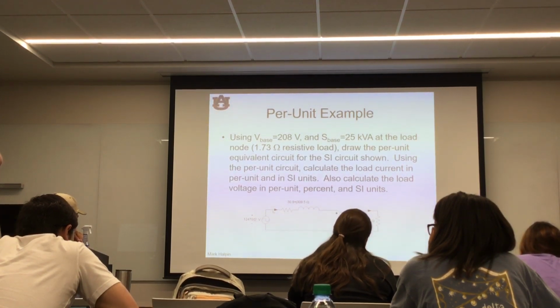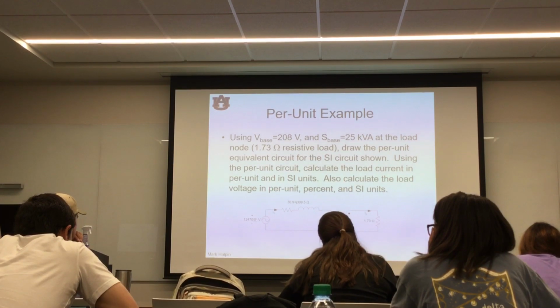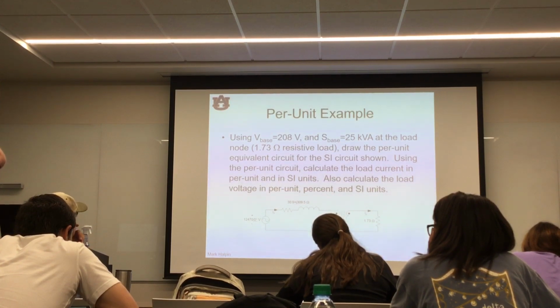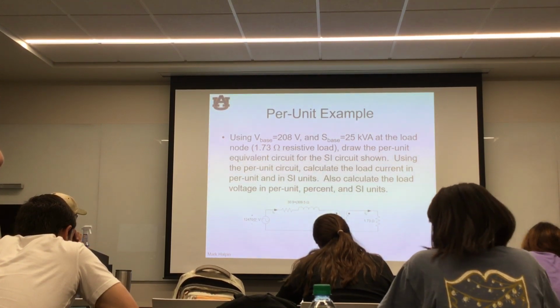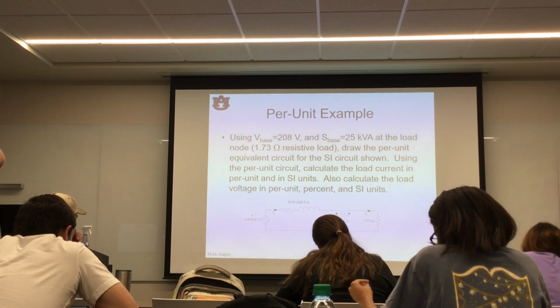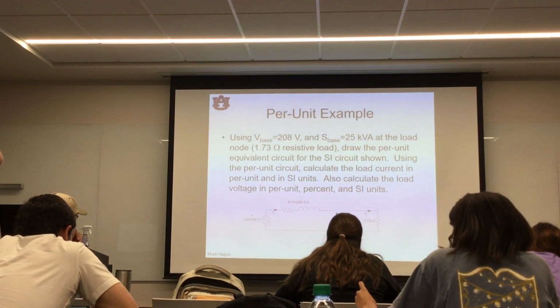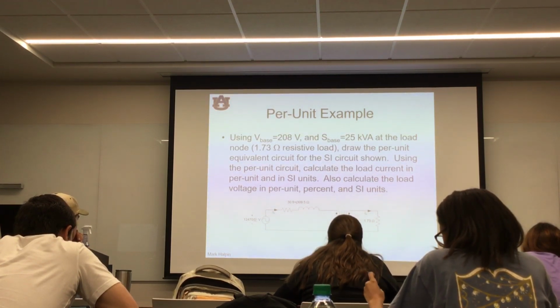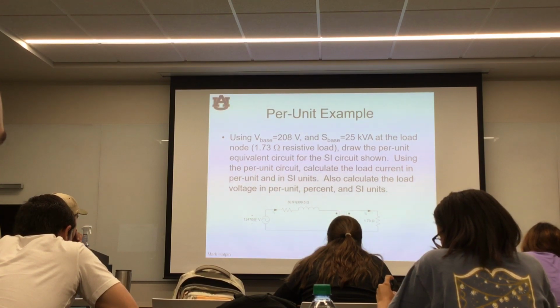Well, 2.4 is certainly not a complex number, is it? I don't know. So in that circuit right there, I see an impedance. It says 30.9 plus j309. But on that nameplate, it just has a number. If I'm gonna calculate something in that circuit, I need an impedance. I need an R and an X. Okay? That ain't on the nameplate. It never is on the nameplate.